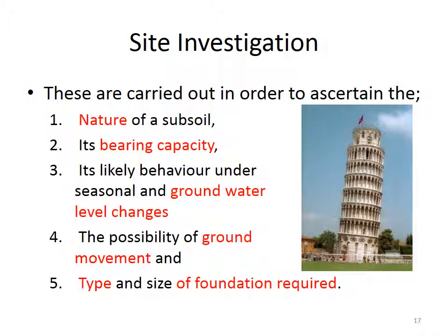So, site investigations. These are carried out in order to ascertain: 1, the nature of the subsoil. So what type of soil is there? 2, its bearing capacity. 3, its likely behaviour under seasonal and groundwater level changes. So in other words, if we start excavating down and we see that the water table is quite high, this could be an issue. 4, the possibility of ground movement. That's why we need to ascertain what type of subsoil it is. And 5, the type and size of foundation required.